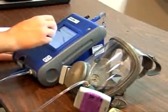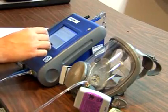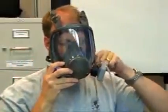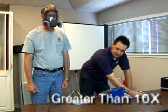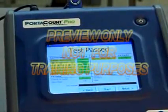The relative workplace exposure level determines what constitutes an acceptable fit and which fit test procedure is required. For negative pressure air purifying respirators, users may rely on either a qualitative or a quantitative fit test procedure for exposure levels less than 10 times the occupational exposure limit. Exposure levels greater than 10 times the occupational exposure limit must utilize a quantitative fit test procedure for these respirators. Fit testing of tight-fitting atmosphere-supplying respirators and tight-fitting powered air-purifying respirators shall be accomplished by performing quantitative or qualitative fit testing in the negative pressure mode.